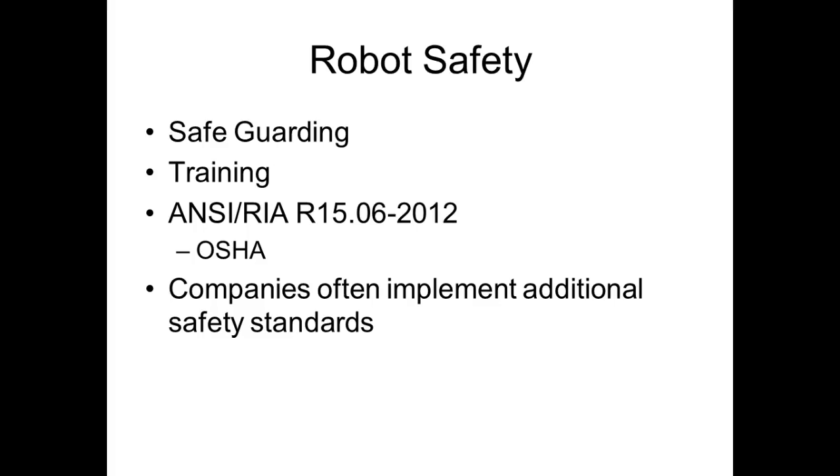which identifies what safety requirements there are and where the stop buttons have to be located. If you look at every one of these robots, there's the big red mushroom button we call an emergency stop button. You'll see there's one on the teach pendant and one on the controller. That's the minimum requirement RIA says for where these stop buttons have to be. But how many stop buttons can you have?